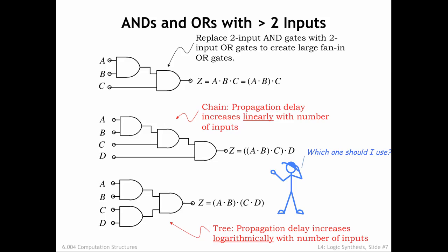The moral of this story? It's hard to know which implementation of a subcircuit, like the 4-input AND shown here, will yield the smallest overall TPD unless we know the TPD of the circuits that compute the values for the input signals.